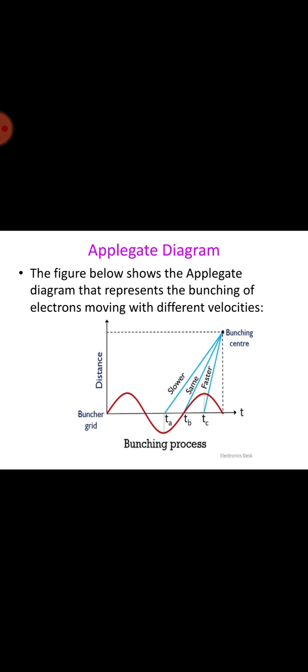Now let us see the beam focusing concept of the klystron amplifier. The klystron action depends on a long thin electron beam through the interaction region. Because electrons carry negative electric charges, they tend to repel each other, causing the beam to spread. So a magnetic field parallel to the electron path is used to overcome the beam spreading. In low power klystrons, a series of small permanent magnets, each forming a magnetic lens, is placed along the electron path. That you can see in this figure.